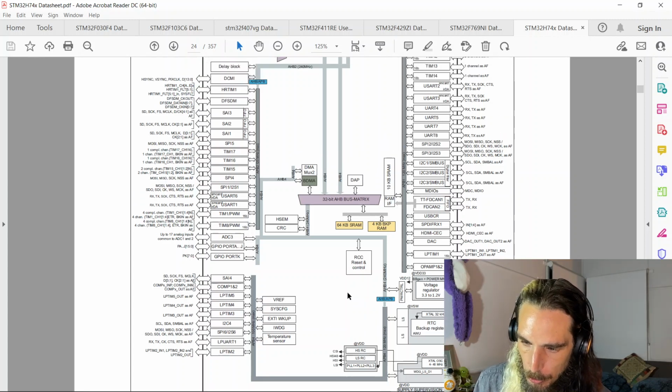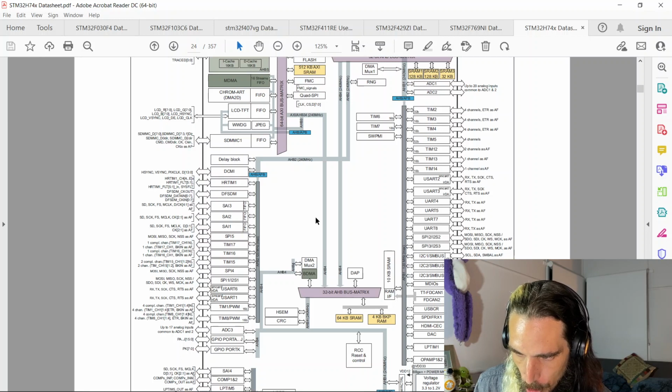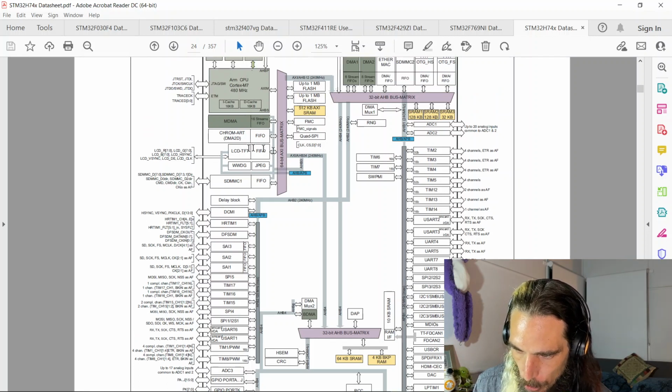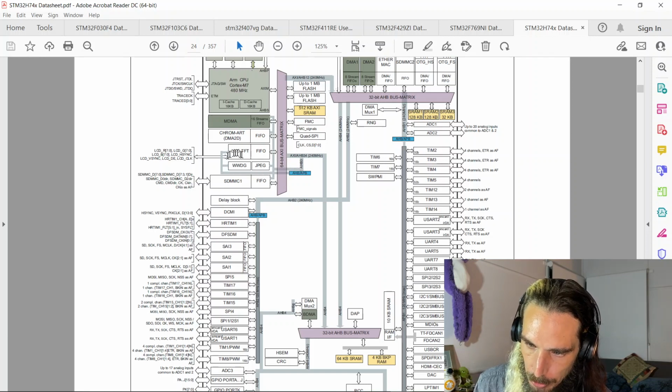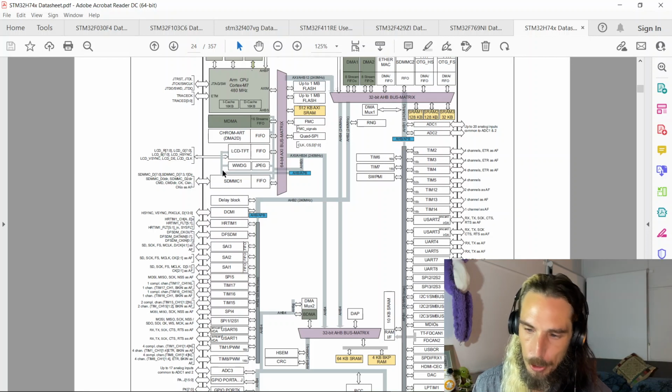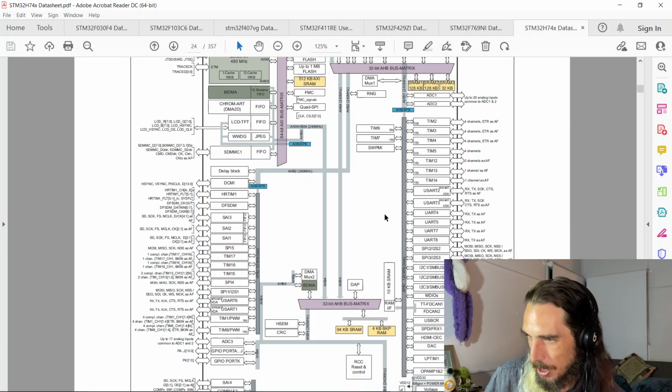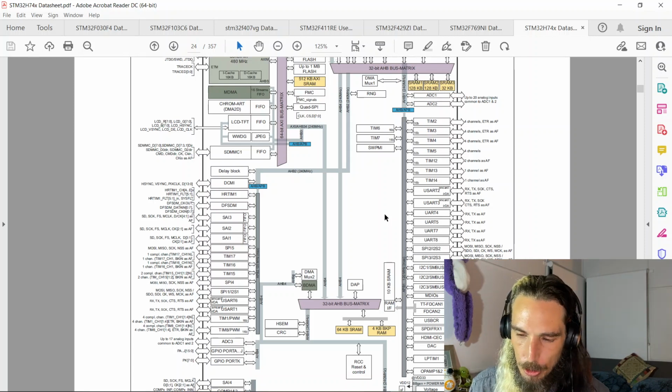And we also have a third peripheral bus, which is hiding at the moment, which is over here, not shown that well on the diagram, but we've got AHB3 here, which goes through an AHB to APB connection, and this grey line here going off to the LCD TFT and windowed watchdog is actually our third peripheral bus. So much more complicated. And peripherals are connected in a way that you can leverage different levels of performance in a way that you can't with some of the smaller devices.